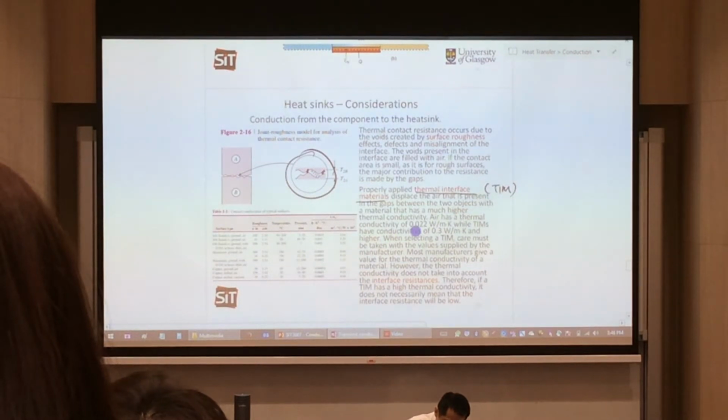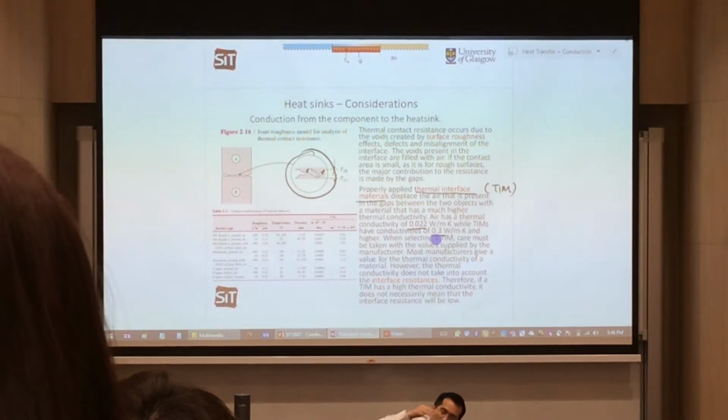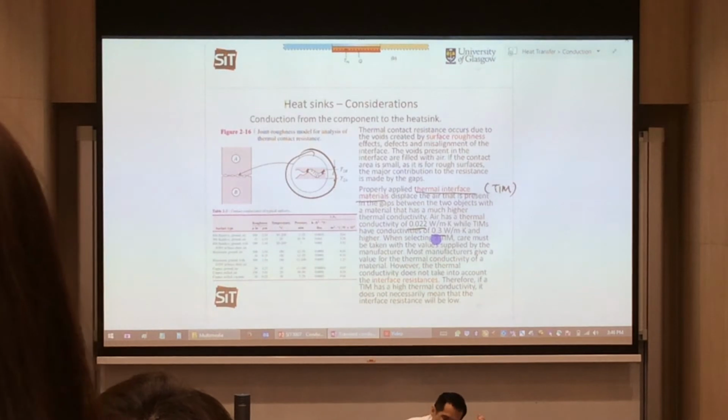The air thermal conductivity is 0.022, whereas TIM's is 0.3. So you can see that there's a great improvement in thermal conductivity if you fill in those small little air gaps with TIMs.